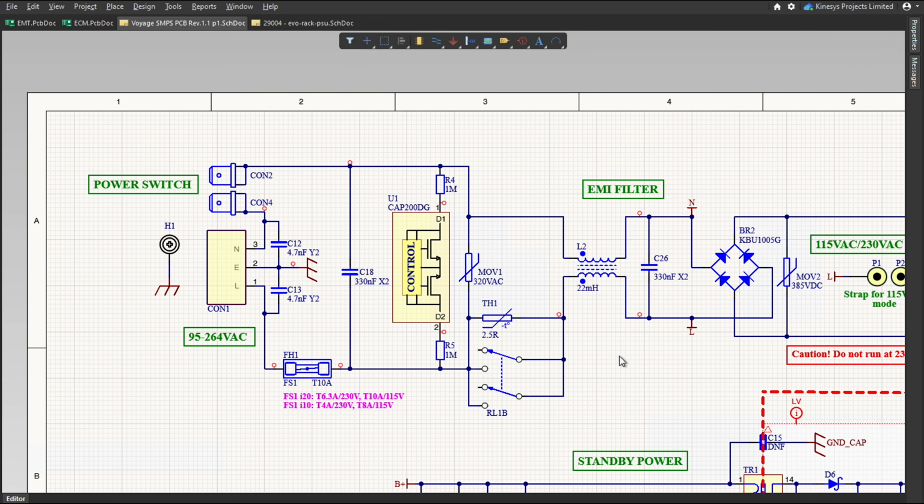A thermistor is a resistor that varies with temperature. So when the power supply is first plugged in, there is a high potential of an inrush current going through the system, but at this time the thermistor is cold, so it will have its maximum resistance, which in this case is 2.5 ohm.